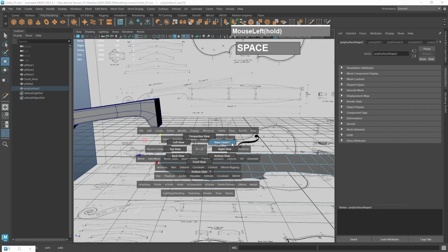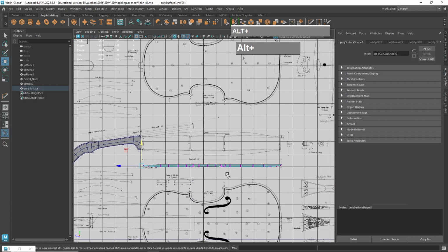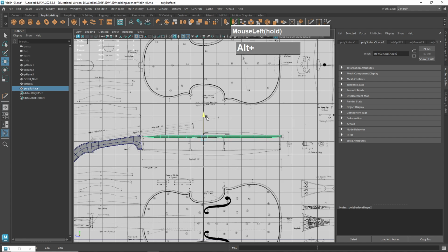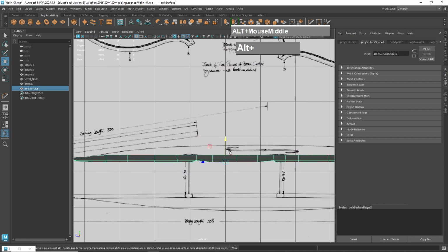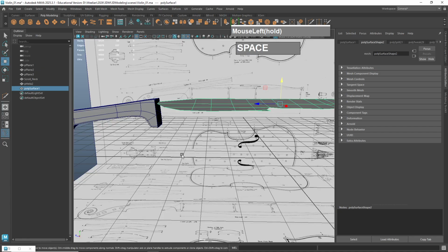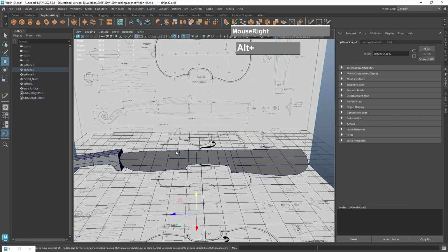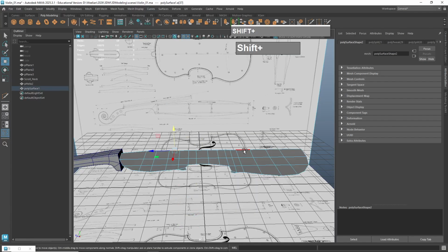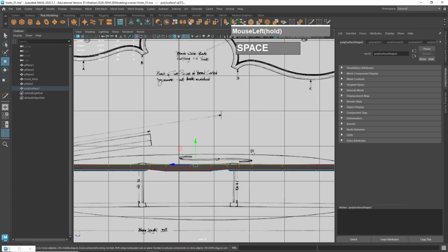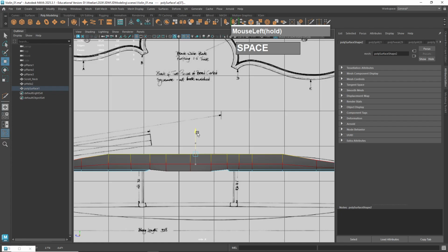So now I'm going to use my right view. I'm going to move this entire piece here, go over to object mode. Move it until it's right at the edge here like that. And you can see the center portion here bulges out quite a bit. Alright, so I'm going to just grab the center vertex, or rather the center edges, right about maybe here. And then maybe I'm going to turn on soft selection, press B, holding down the B and then mouse click, and then gradually let it influence the rest. Then just pull this up until it reaches here.